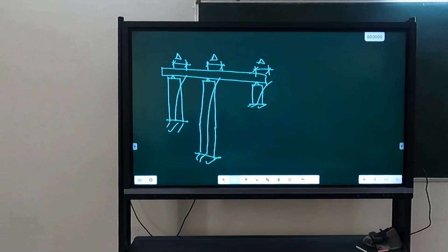When you calculate for the ground story, you will consider the gravity load of the 5 stories also, because the gravity load will also flow downward. So in the ground story column, the P will be 3 times. So the P delta effect you will calculate accordingly, and your story V versus delta curve will change.